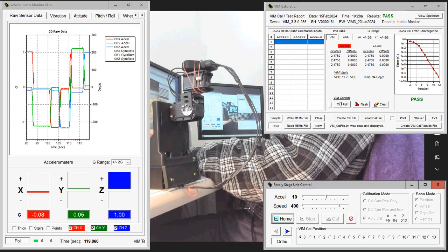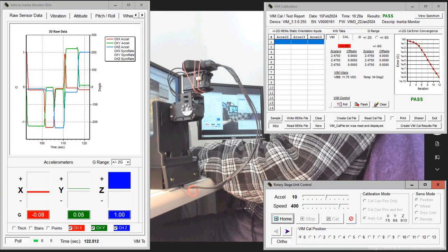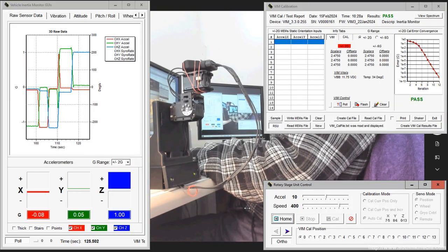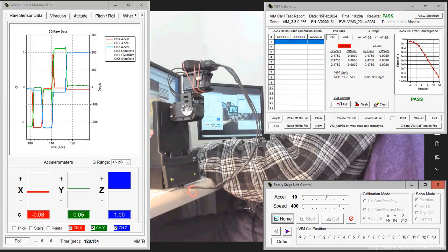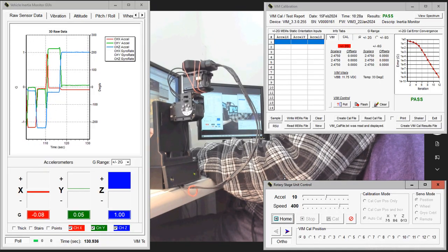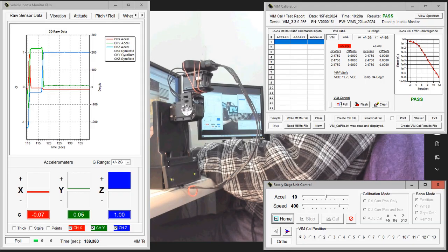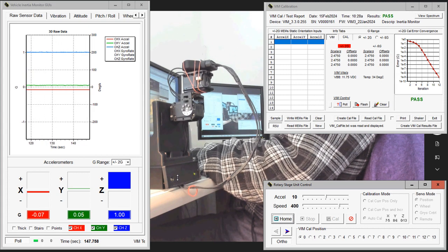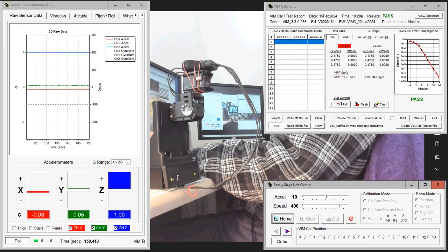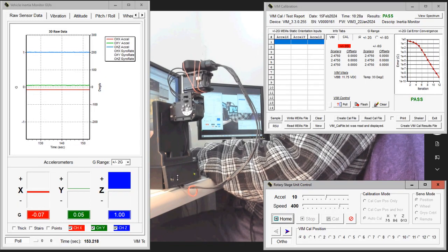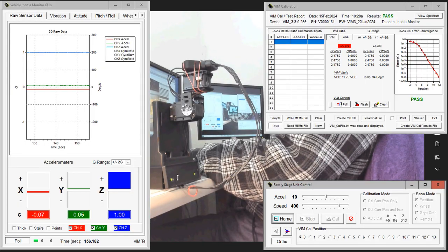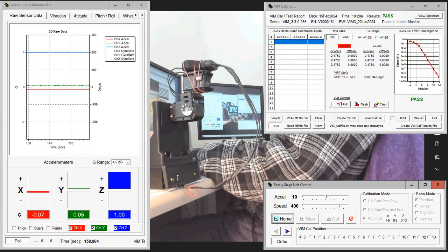The method of the calibration involves Jacobian error estimates along with a Hessian error matrix to be able to resolve and calibrate the X, Y, and Z axes without requiring the rotary stage unit calibration test apparatus to actually be level. The technique uses minimization of errors received from X, Y, and Z corresponding to just one input, the gravitational constant of the Earth.